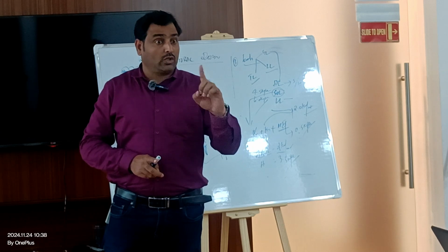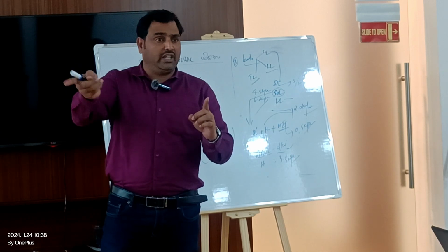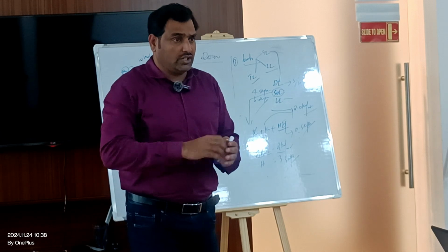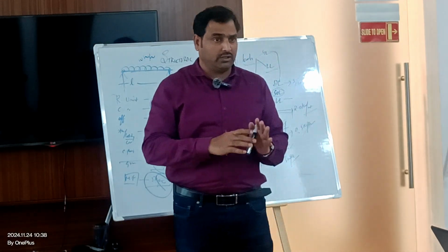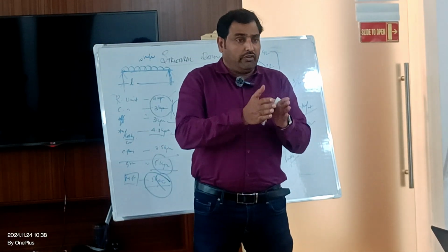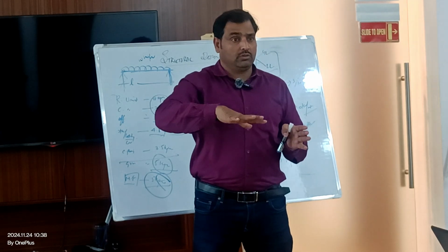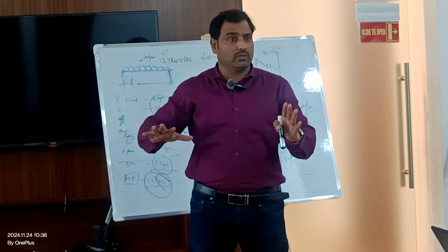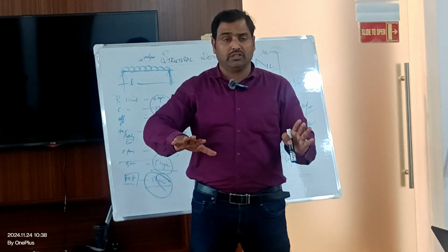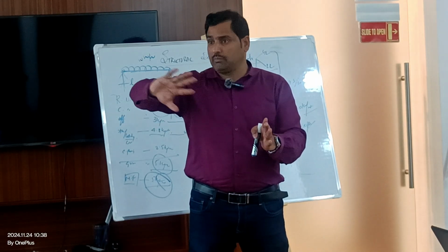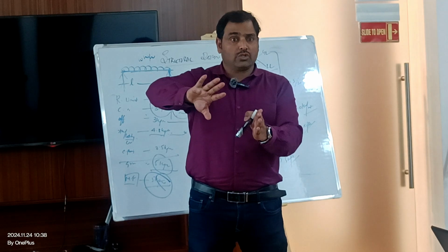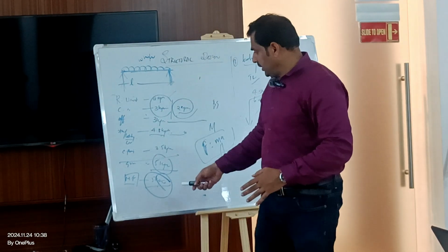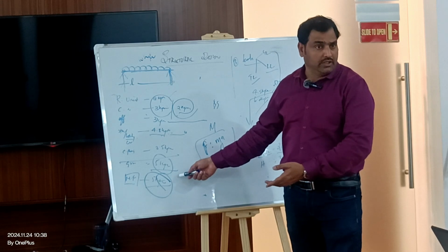But what the code says is, if it is more than 5, directly take 100%. You don't take it because the authority does not require it. 100% is required by the authority when you have a complete mechanical floor. If it is a complete mechanical floor, where I have pumps and mechanical equipment, then the load is actually 7.5. When it is going more than 7.5, then take 100%. That is the reason why the gym, which is included, is 5 kPa.